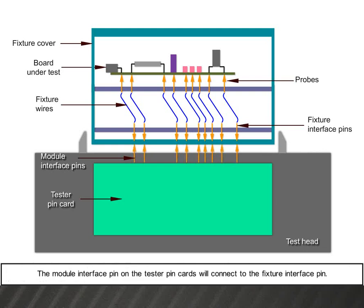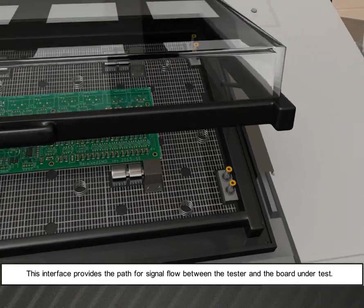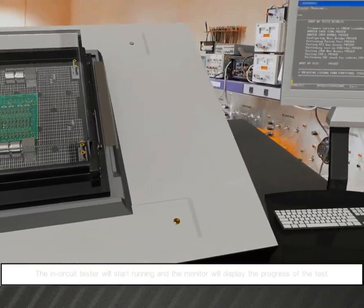The module interface pins on the tester pin cards will connect to the fixture interface pins. The fixture interface pins are wired to the probes which connect to the board under test. This interface provides the path for signal flow between the tester and the board under test.